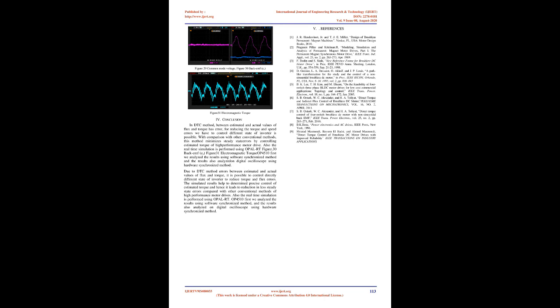For conclusion: in the DTC method, there is an error between estimated and actual values of flux and torque. For reducing the torque and speed errors, we have to control different states of the inverter. In comparison with other conventional methods, this method minimizes steady-state errors by controlling the estimated torque of a high-performance motor drive. Also, the real-time simulation is performed using Opal-RT OP4510. Figure 30: back EMF, EA. Figure 31: electromagnetic torque.